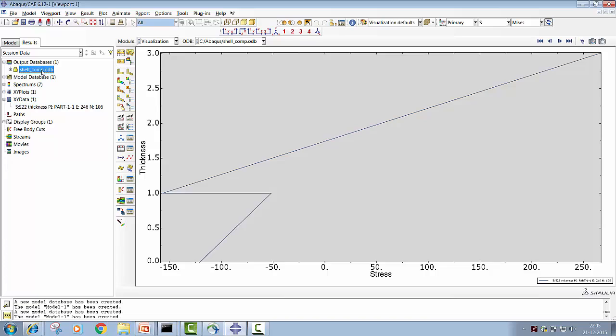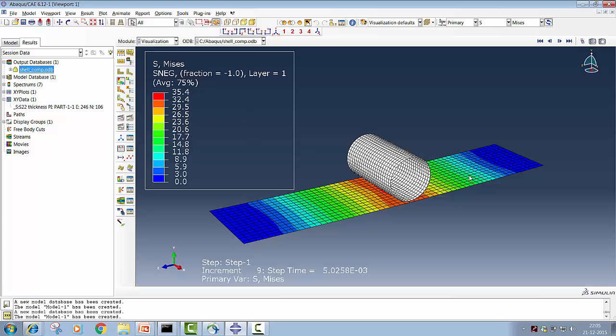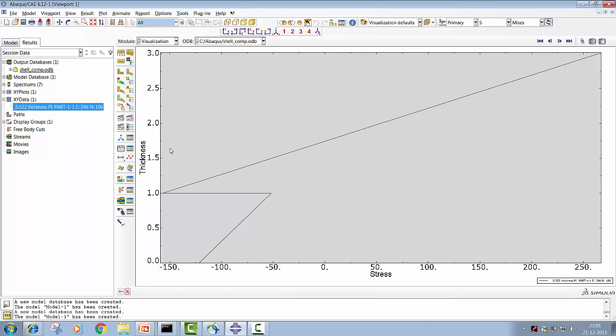If you imagine the plate subjected to center bending or center loading, it will be under a bending load, and due to this the top layer is in compressive bending stress and the bottom layer is in tensile bending stress. As this is a dissimilar material with a different modulus of elasticity as well as different thicknesses, the bending stress plot will not be linear.